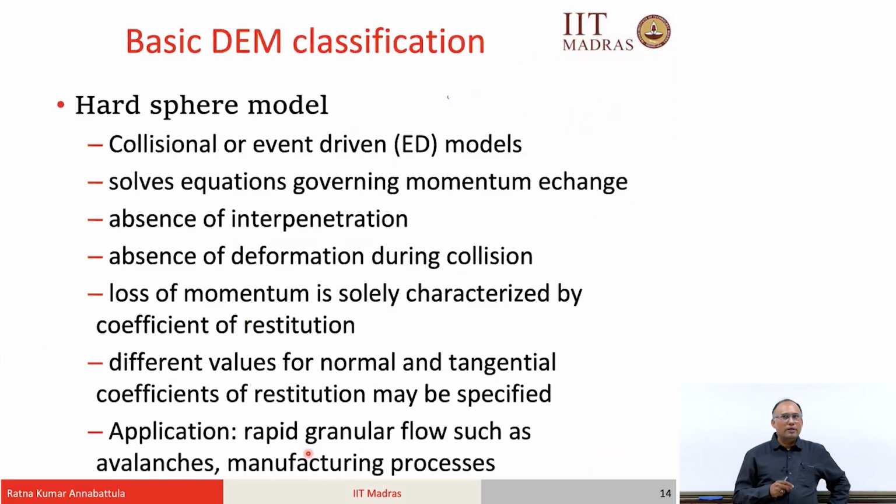So, now there are 2 main variants of DEM simulation. One is a hard sphere model, another one is soft sphere model. All that we were talking about till now was a soft sphere approach. Now, let us look at the hard sphere model. These are also called event driven models or collision models. It does not let the contact have any interpenetration. These are all hard spheres, there is no deformation whatsoever possible, right.